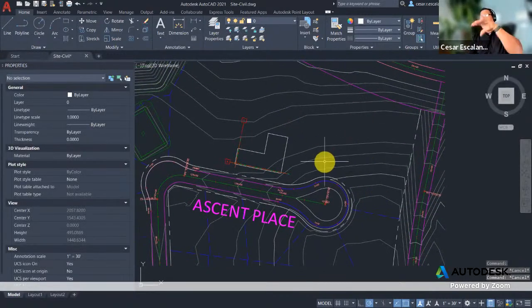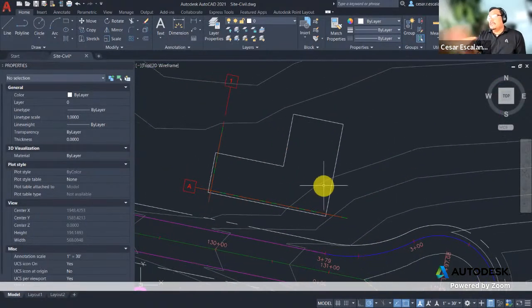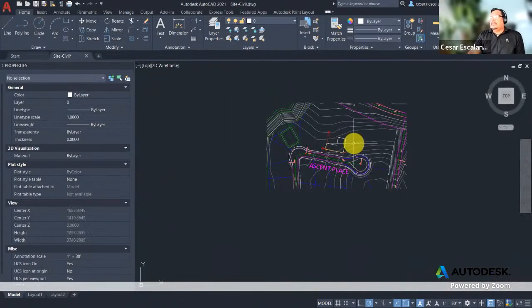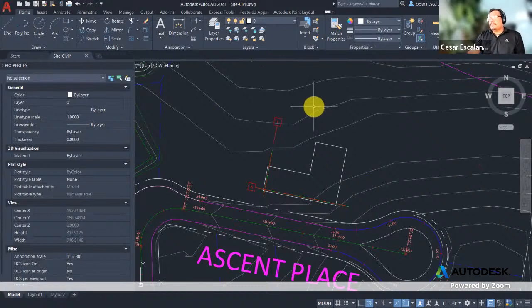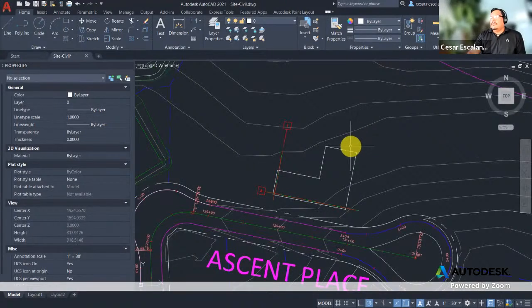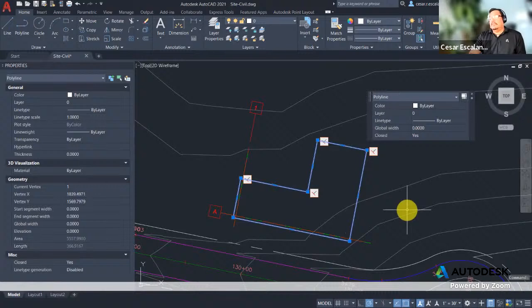It's good to understand what elevation we're talking about, because that's going to define the finished floor of the building. So the civil or survey file usually sends us a CAD file with the elevations, and we need to have an idea what will be the ground elevation of the building. This information is something that you need to work out with your civil engineer.